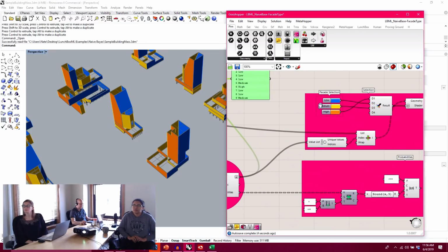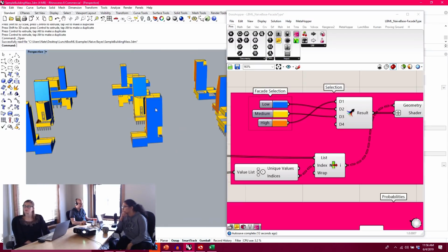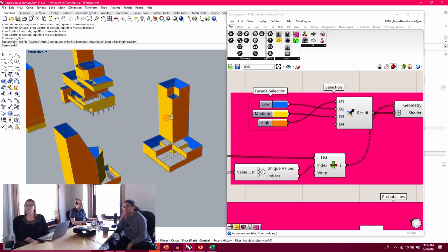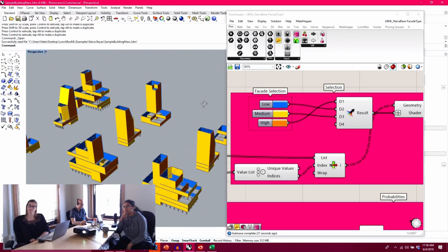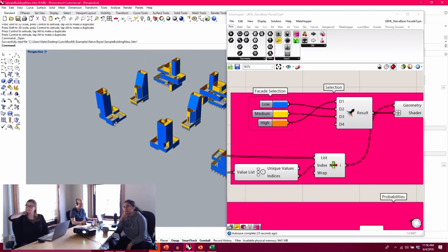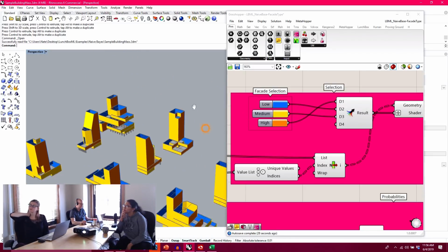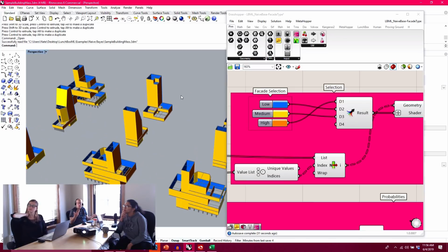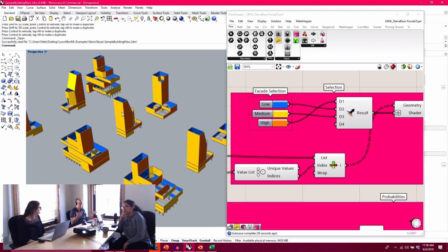And I'm over here selecting the facade and coloring it based on what's being selected. So the blue ones are lower performing, the yellow ones are medium, and these are high performing. So based on the orientation, you actually start to see this algorithm figuring out how these facades should perform. And from an intuitive standpoint, because of the way we've trained it and set this up, it has a passing similarity to some type of solar analysis, but it's not doing any form of simulation. It's just using data to predict certain outcomes.